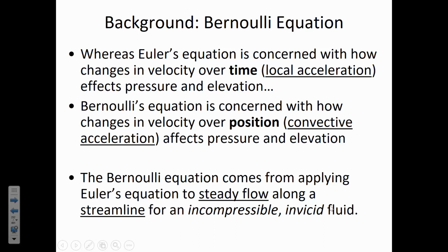If you look at these last two assumptions, in some ways there's a tension there, where Bernoulli's equation is more accurate the better you honor these assumptions. Now, the sad truth is there are actually no conditions where Bernoulli's equation applies perfectly, because there's no fluid that's both entirely incompressible and entirely inviscid. No fluid meets those two constraints. But we can sometimes get okay results with Bernoulli's equation. Sometimes it does a pretty good job estimating, as long as we keep in mind what these restrictions are, and we only apply Bernoulli's equation in situations that are pretty close to honoring these restrictions.